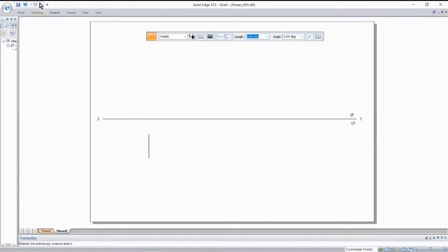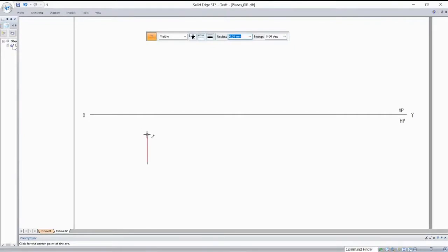Then use your compass. Hopefully you're doing it along with me. Tell me if I'm fast. Before that, let me change the thickness of the arc. What I'm drawing is thin. The arc must also be drawn with a thin line. Then with a 25 radius, cut an arc here. After that, join it. And it should be joined with a thick line.